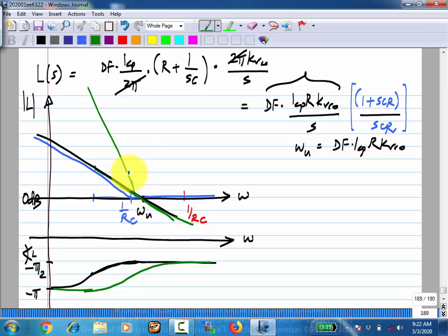All of you have gone through some course which teaches you basics of negative feedback, right? So you know what phase margin is. So when the gain crosses unity, you look at how far phase is away from minus pi. Because if the gain is unity and phase is minus pi, then it is unstable, right? You will have poles on the j omega axis and it will be an oscillator. So a measure of stability margin is to see how far it is away from that. Okay, that is you look at where the gain magnitude is 1, but how much the phase is away from minus 180 degrees.